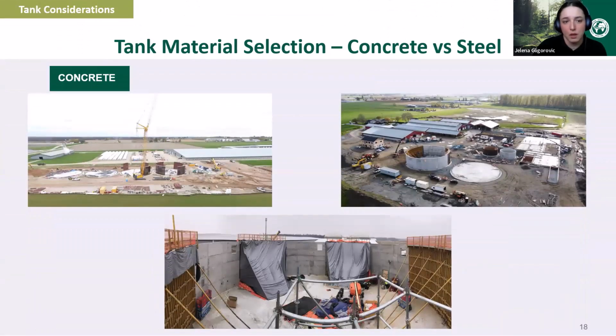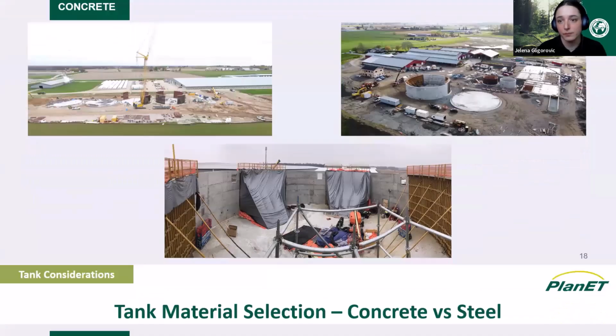I just have some photos here of the concrete versus steel tanks in the construction process. One thing to note on the bottom photo here, you can see how we've had to protect the concrete from the weather conditions when it was being poured and cured due to the lower temperatures. This can be a little costly, so something to consider again for construction schedules and whether concrete or steel is preferable, but of course concrete is more flexible in the sizing and can be buried, so a number of different factors to think about here.